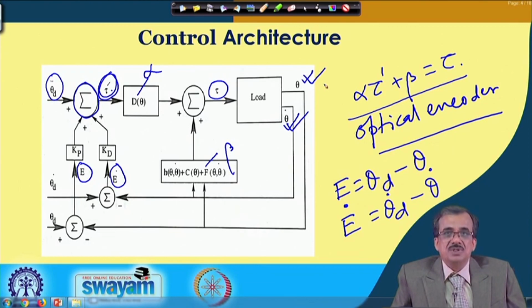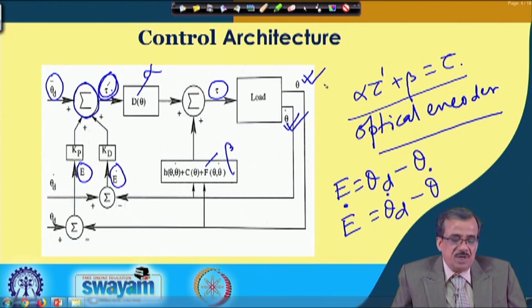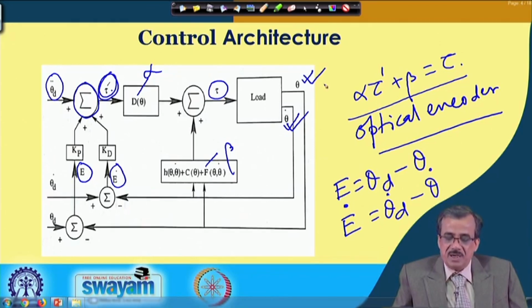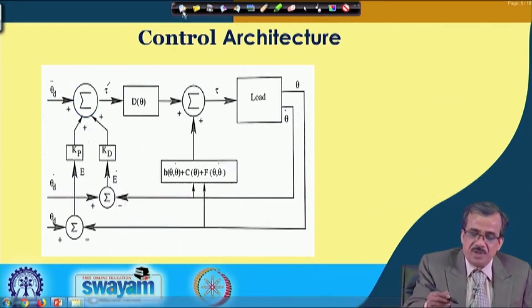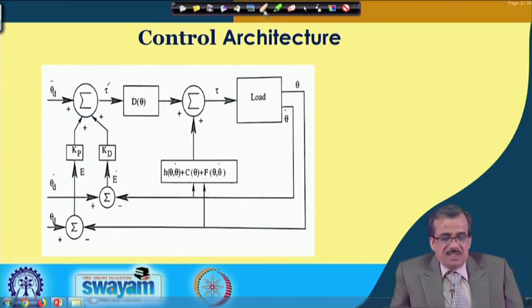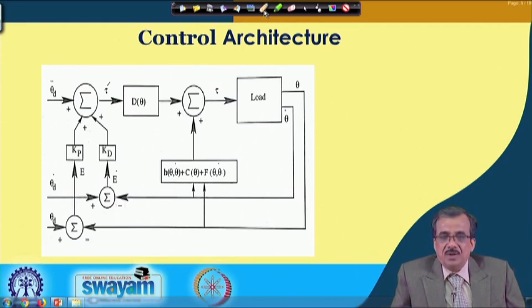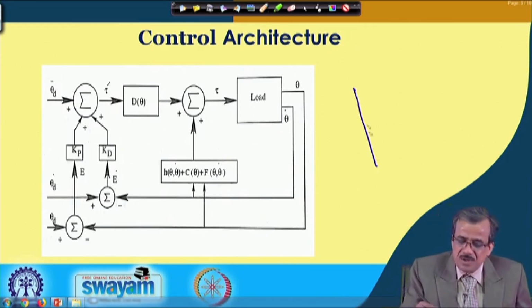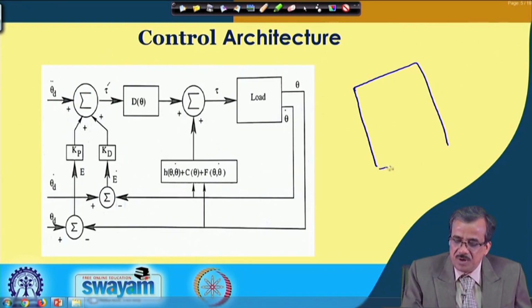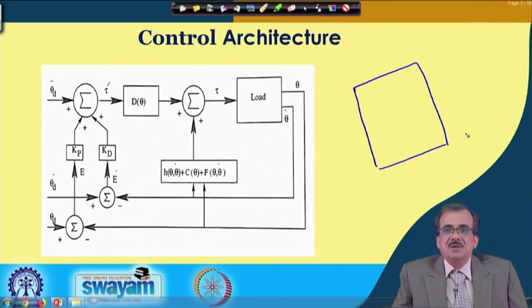Now, my question is how to use the principle of fuzzy logic and neural network to design and develop the adaptive controller. That I am going to discuss now. To design the adaptive controller so that it can generate the gain values k p, k I and k d in an adaptive way, you can design one fuzzy logic system or utilize one multi-layered neural network.